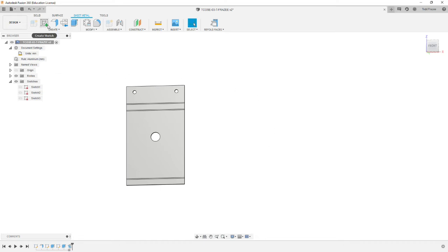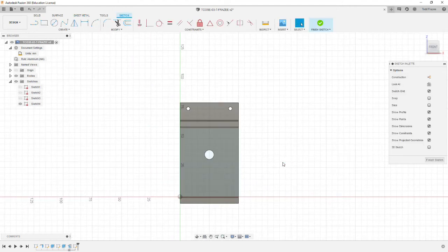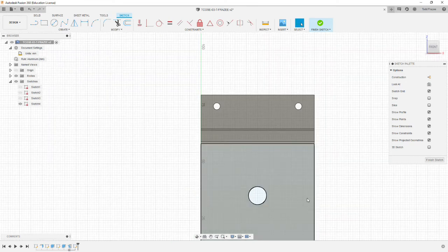Now we're going to create a sketch in the plane of the part, the top of the part. And we're going to establish the tapered cuts on the sides. Now the drawing's ambiguous. It doesn't show a vertical dimension for the taper that hits this side wall, but it does appear to be in line with the center of the whole 8 millimeter hole we developed. So we're going to go ahead and make that assumption.